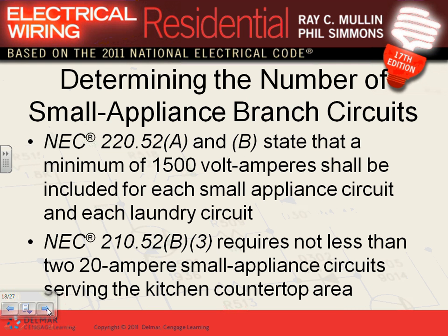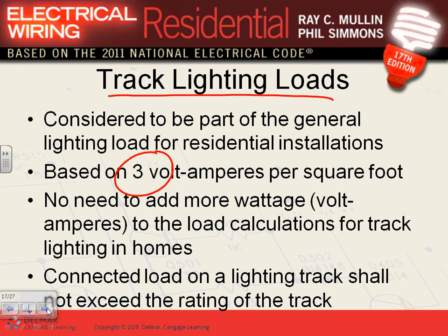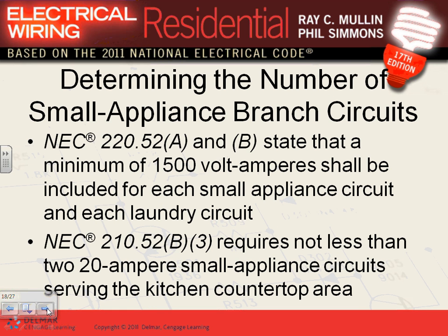Connected load on a track like that, basically saying you can't put more bulbs in it than the track allows. Then, yeah, absolutely. I don't know how you violate that other than doing that. All of them have a rating, the largest wattage that you can put and how many heads you can put in this track. Then they have little protection devices, an optional thing you can put into the track, so if you are overloading it, it will trip.